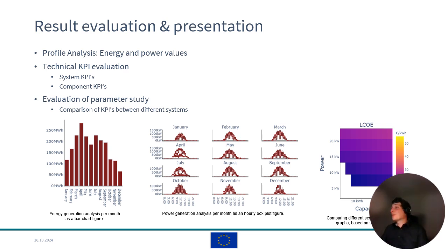And there you can see which levelized cost of electricity comes out when combining those two different sizes of the battery and the converter. And you see that it gets lower and lower the larger the battery and the converter is, basically in this example.